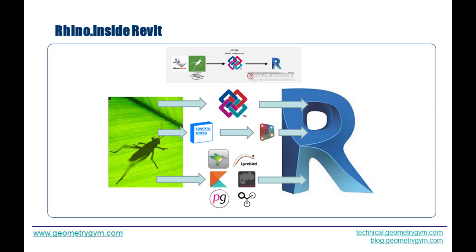There's a million different ways. There's 10 or so plugins that have been developed for this exact thing. Geometry Gym have our own plugin for Grasshopper. People export, go to Speckle, bring that back into Dynamo, then try and build Revit geometry. Our way is to export an IFC file to your computer and then import that IFC file back into Revit.